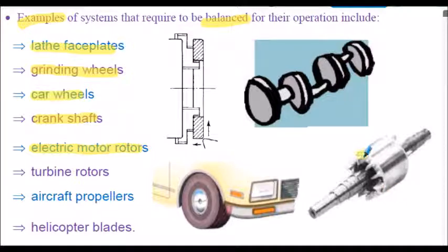This is a rotor here. You can't see it very clearly, but those little pegs are part of the casting. It was an aluminium casting, and those pegs are where they would put steel washers. They would put steel washers on the pegs, and then bang the aluminium spigots flat to tighten the washers on. That's how they used to balance the rotors, because they had to be balanced before they could go into the electric motor itself.